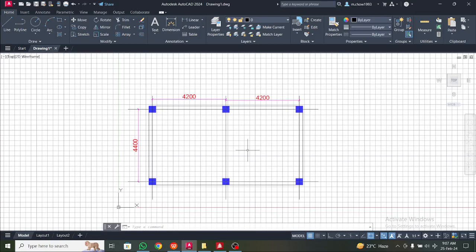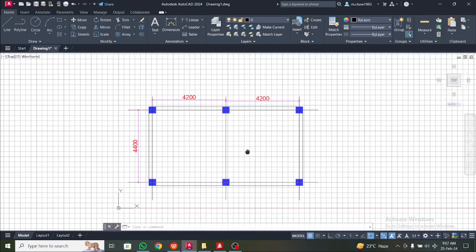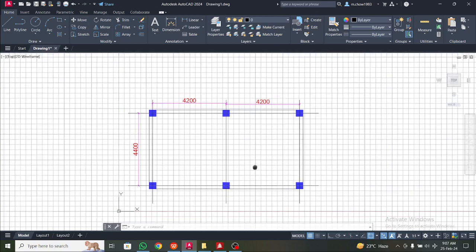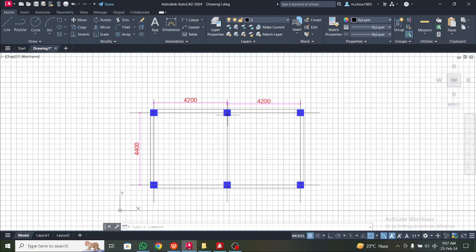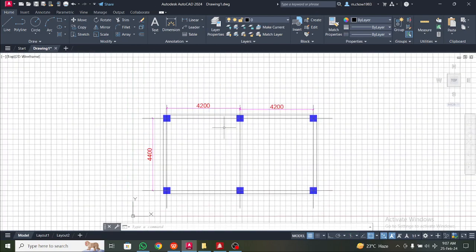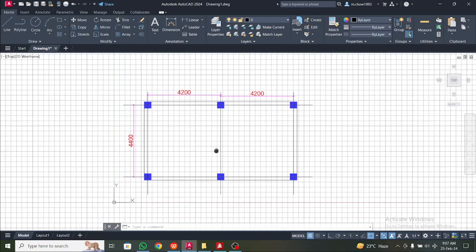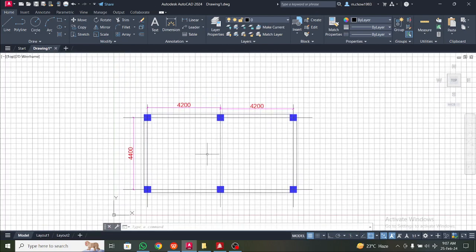Today we will design a building using the response vector method, and I have updated the notes also, which I'll share with you, and I'll also share the STAAD file with you so that you can easily do the load combination and other things. So this is a very simple model. This is a ground floor only building, and we're going to apply the response vector method, and also we're going to see the final results of this using RCDC or the STAAD Advanced Material Designer.